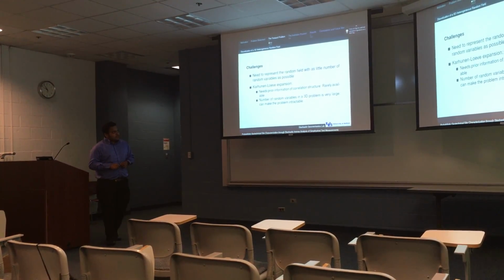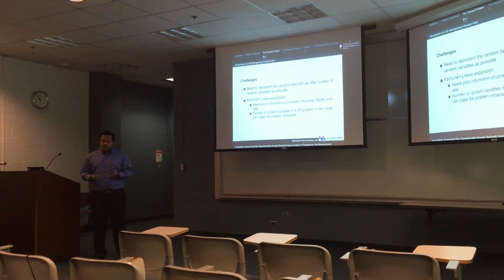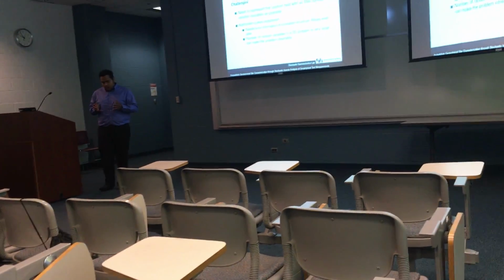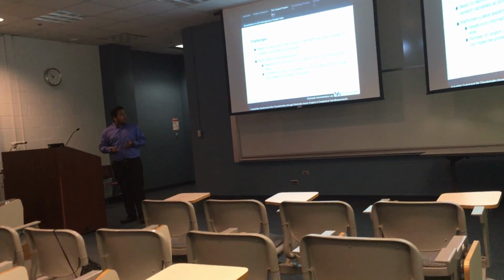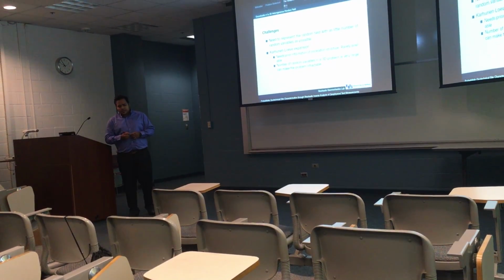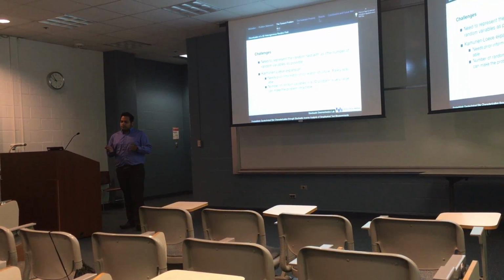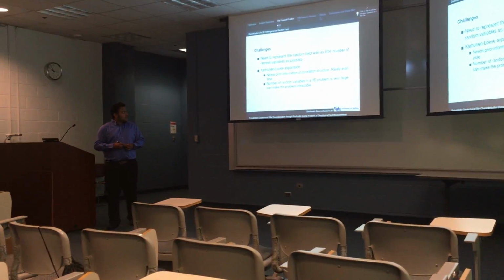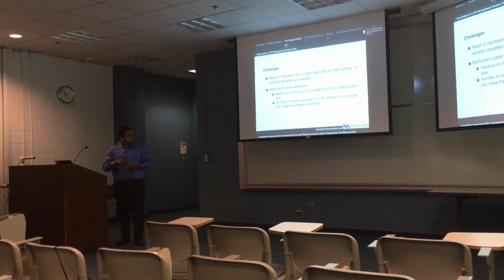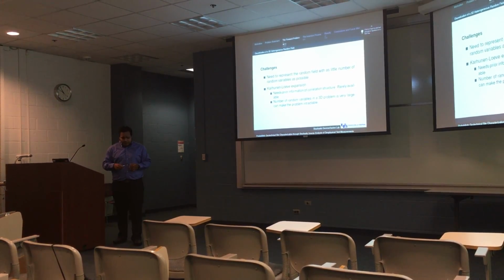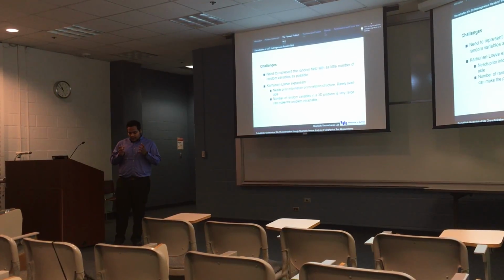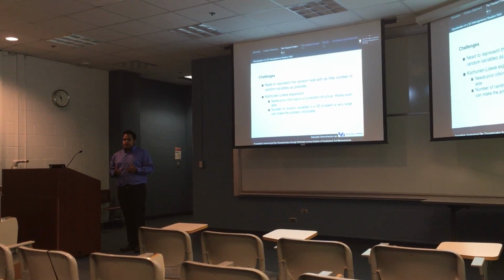Now we go for discretization of the 3-dimensional random field. The challenge is that we need only a few random variables, random parameters, to discretize the whole soil domain. That's because otherwise the problem would be huge and intractable. We know that the KL expansion requires a prior assumption on the correlation structure of the soil.